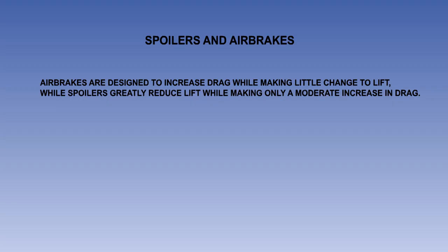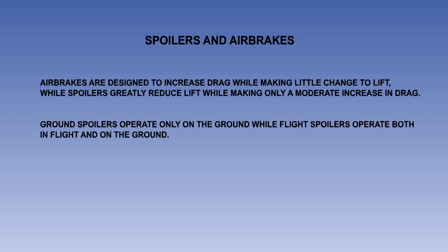That is the end of the lesson. You should now understand the difference between spoilers and air brakes. Remember that ground spoilers operate only on the ground, while flight spoilers operate both in flight and on the ground.